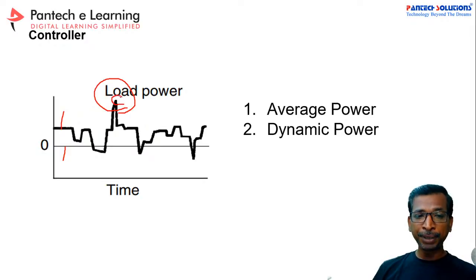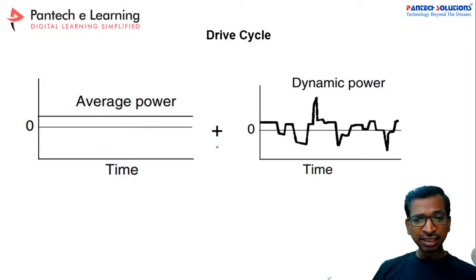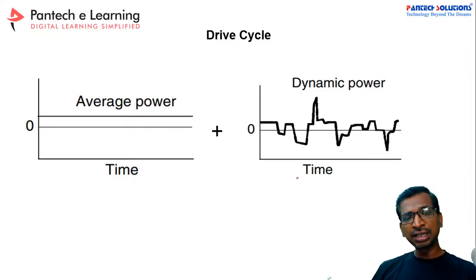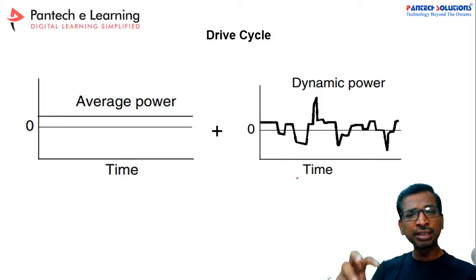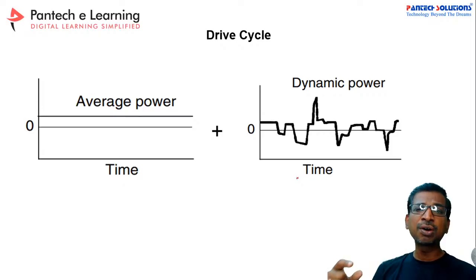Similarly, if you are running at the rated critical speed with very little load, the circuit will work in low power mode. If you take the average, you get the average load power. This is called the drive signal. Based on this drive signal, we can generate a controlled PWM. Here the PWM technology, pulse width modulation technology, is involved to generate proper control for the power electronic circuits.